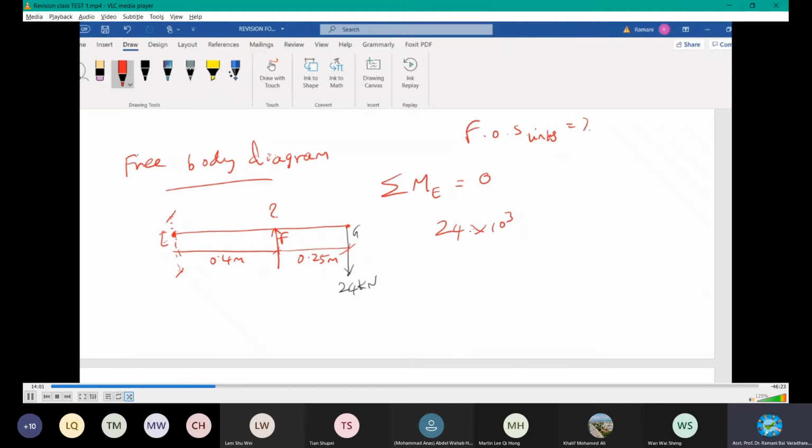Moment. We are taking moment, right? What will be the distance? This is the force times moment will be 0.65 from here to here, right? From this point to this. We are resolving about E. So we will have into 0.65 meters, and then I've done for G, then F. F will be positive or negative? Negative. That is our unknown, right?